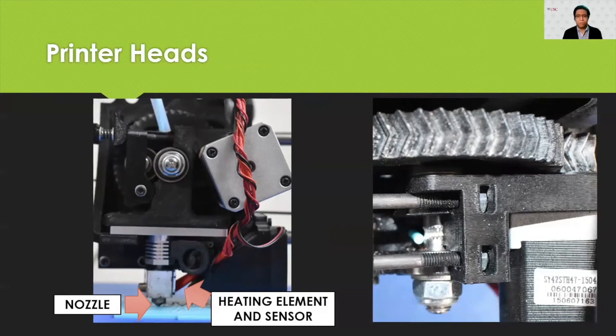Not enough temperature could impede the adhesion between the layers or not melt the material at all. Too high temperature might degrade the material and compromise the strength of the object that we are printing, or even burn the filament. For most applications, these parameters are pre-configured in the software, but we have the liberty to change them if we need to.